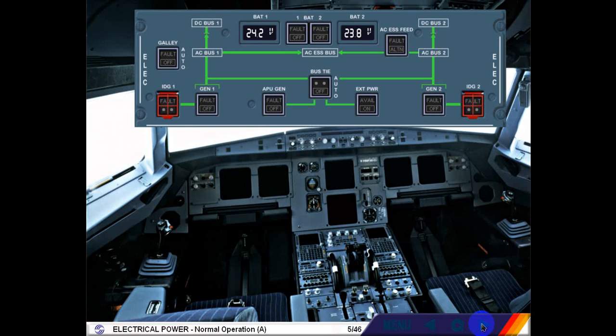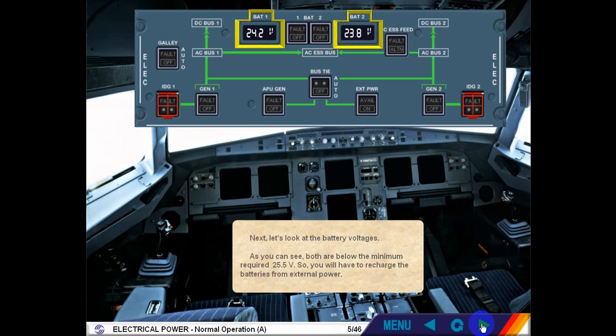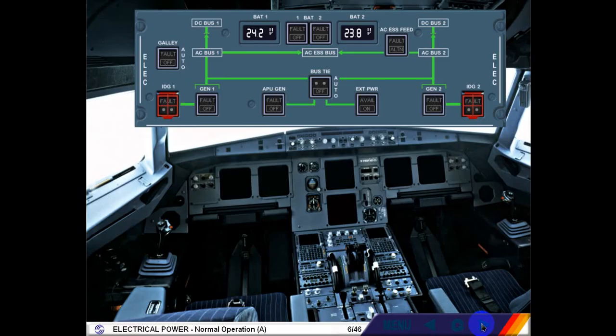Next, let's look at the battery voltages. As you can see, both are below the minimum required 25.5 volts, so you will have to recharge the batteries from external power. To charge the batteries, you have to switch them on.